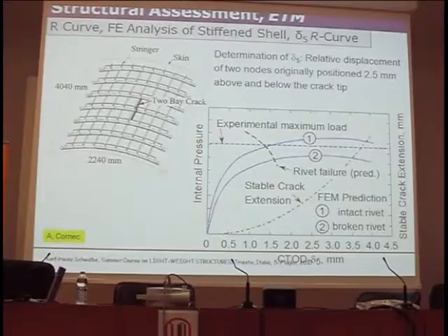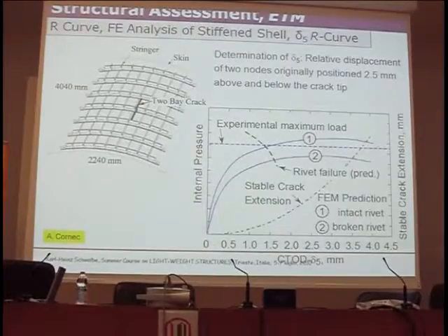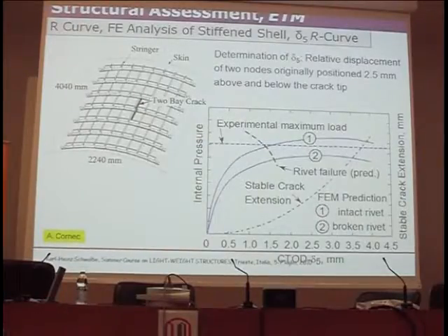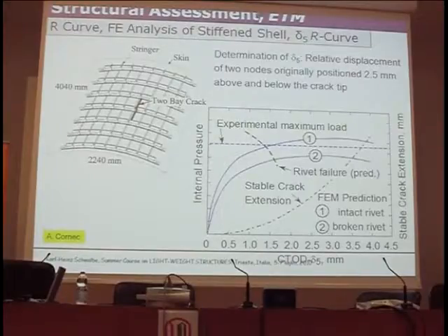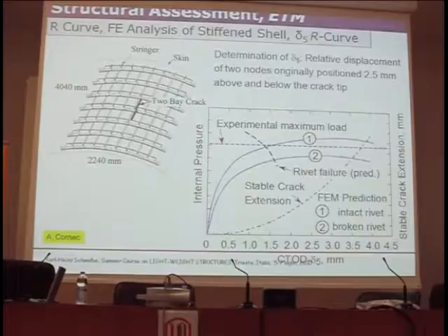But this high pre-cracking load should have had an effect on the result. And indeed, believe it or not, Alfred sat down and did a further run, but with just one previous load cycle, because the whole thing is quite time-consuming, and this had a visible effect again on the final load. So again, get as much information as possible.